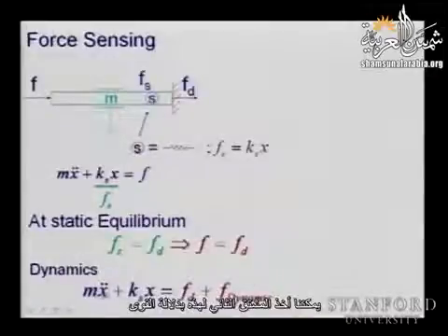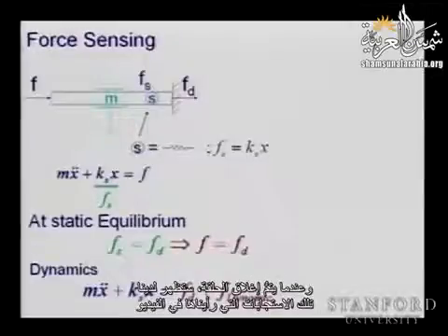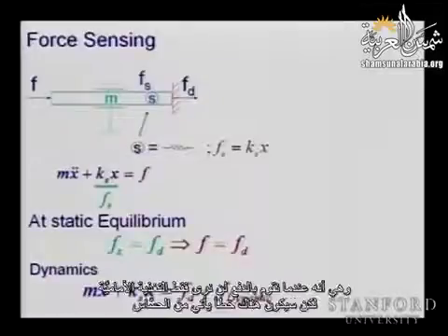So we can take the second derivative of this in terms of forces, and then we will have this stiffness appearing in the equation, and then we close the loop. And once we close the loop, we are going to have the responses we saw on the video. That is, when we push, we will see not only the feed forward, but there will be an error coming from the sensor, and this error will produce torques to move the robot in a way to reduce this error.